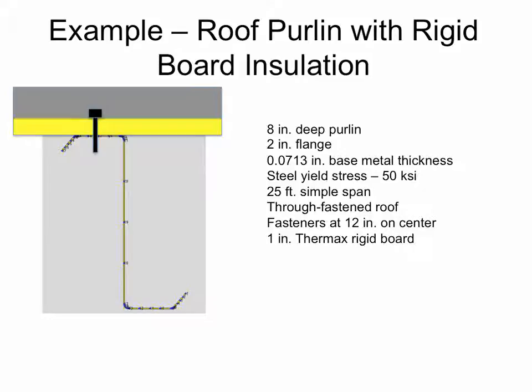Yeah, so I think if you had these at 12 inches on center, you'd probably assume that it was fully braced, right? So you would just do the checks for local buckling and distortional buckling. And for this type of section, maybe you don't have local buckling controlling. Distortional buckling, because you're connected to the panel, you could maybe get away with that. And so you'd probably get close to the MY for the capacity, right? But